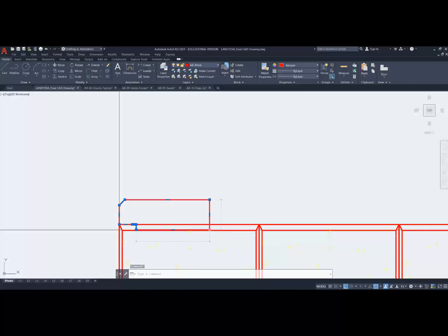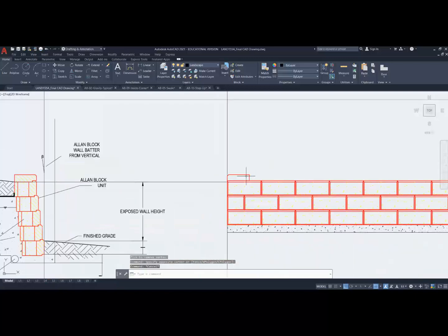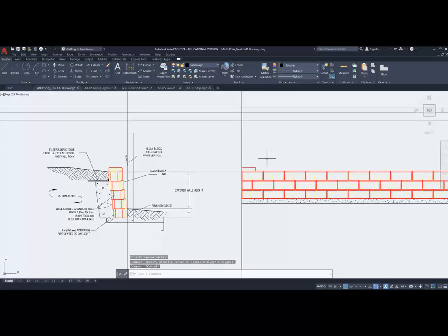So I'm going to move this up. Now, again, this is a polyline, so there's a couple of ways of treating this. I'm going to see if I can just remove the vertices, so it lines up in here. I only need two in here. It's just cleaning up my drawing. That's all I'm doing, is cleaning this thing up. And by removing all those vertices, it's now a single line from one side to the other. Beautiful. That's what I want.